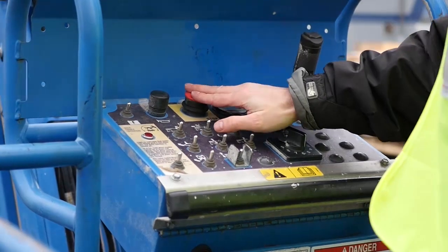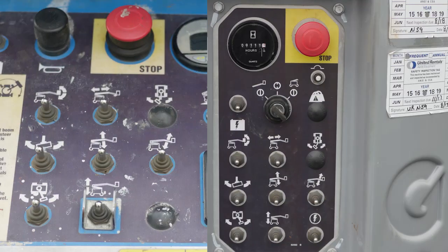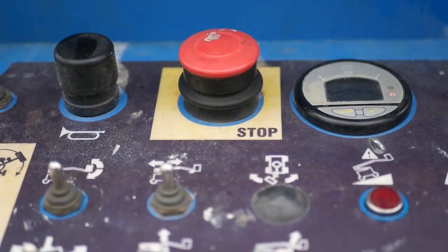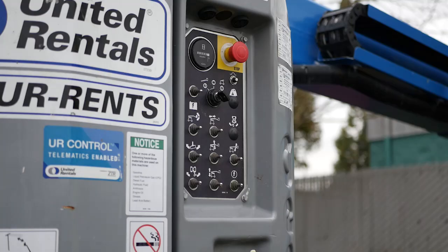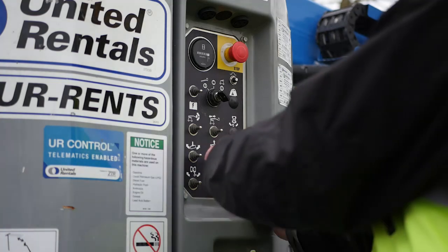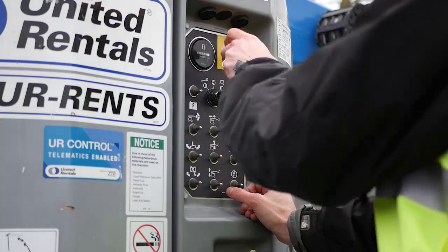Pressing the emergency stop will stop the vehicle. There is an e-stop on both control boards. If for any reason you feel unsafe, just press the e-stop, and notify a supervisor. If you find the vehicle controls unresponsive, check the e-stop on the platform, and ground controller. It is likely one of them has been pressed.